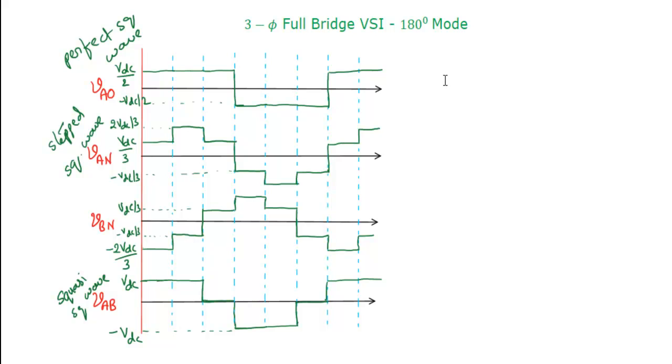So that's why we will consider the line voltage to calculate the output voltage. So here output voltage is V0 RMS line. Okay. So that is equal to, as I think you all remember about that, how to calculate the RMS value from the waveform. That's what we discussed in the beginning of the class. This is segment 1, this is segment 2, and it is a kind of symmetrical waveform. That's why no need to consider the second half cycle. First half cycle is sufficient.